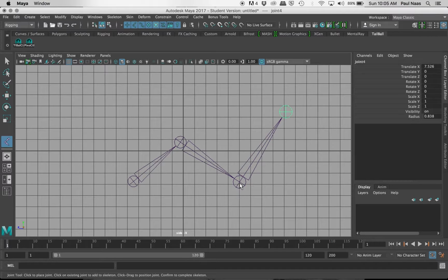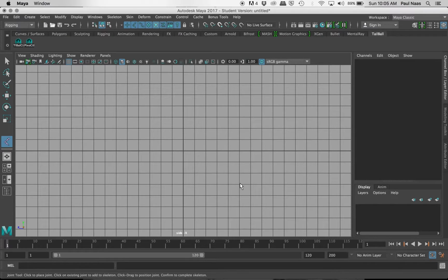The next joint in the chain orients the previous joint down the length of the bone, which is very important. You always need an axis that runs down the length of the bone so that you can rotate around that axis. So when we create our joint chain in our character, we're always going to create an additional joint at the very end of the chain that really doesn't do anything except orient the previous joint in the chain.